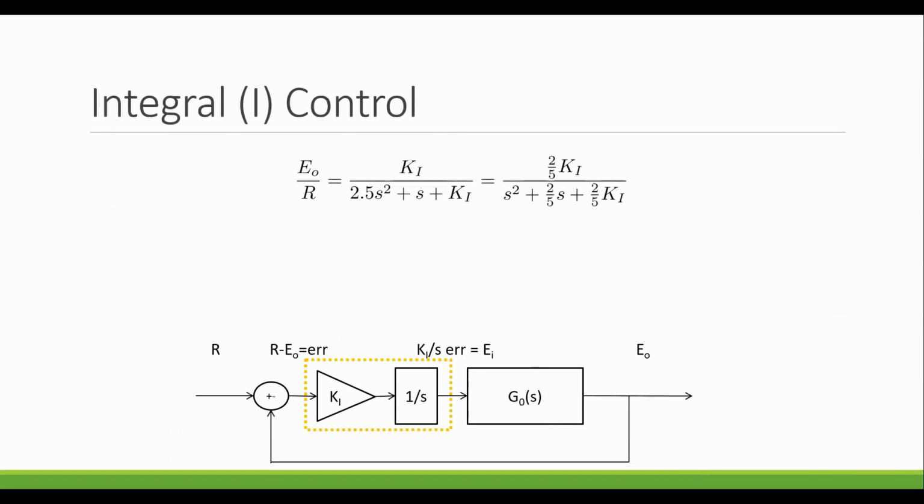So once again, we have created in the closed loop system a second order system. So it's potentially going to have oscillations, a peak time, and an overshoot that with the proportional controller we didn't see, because that was first order. With the open loop system we didn't see them either, that was first order. But again, this is second order.